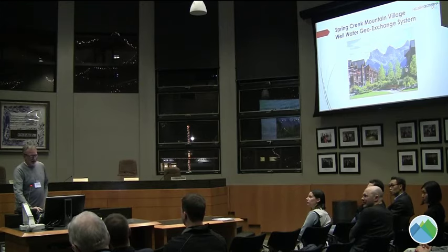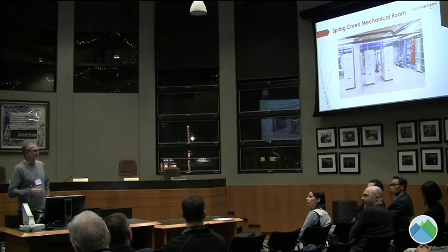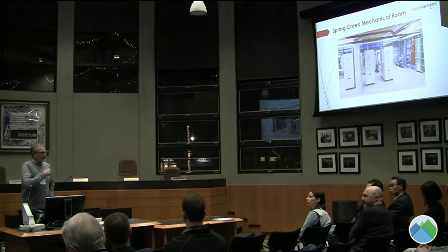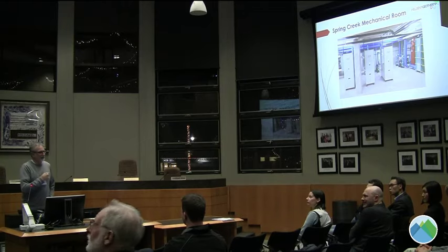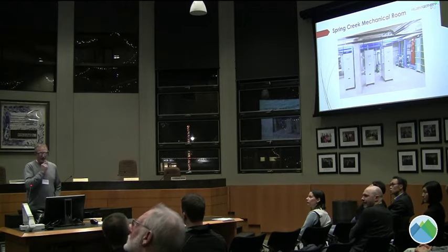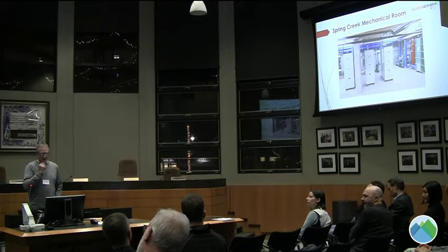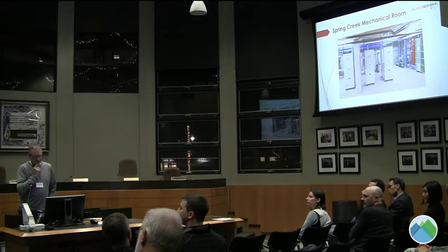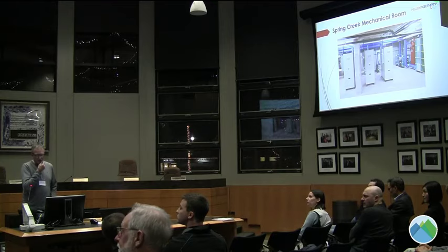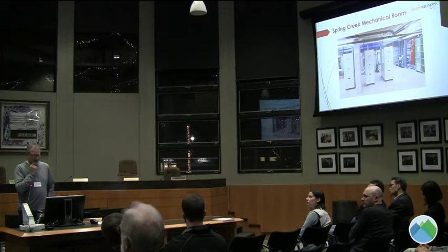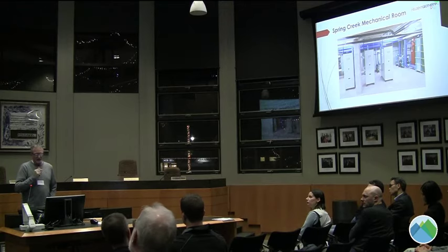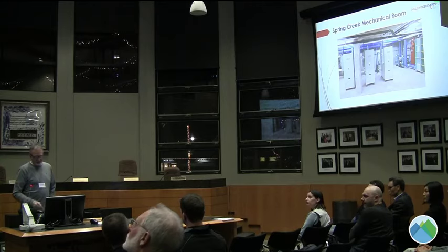Because geo doesn't degrade the water at all. 100% of the water that comes out goes right back in, just a few degrees cooler or a few degrees warmer depending on the season. So it's totally non-degrading, and there's no contamination or anything like that at all. So this slide is just of one of the mechanical rooms of a 50-unit apartment building down there. It's a 90-ton system, so it's 3 30-ton heat pumps, and you can see the heat exchanger and the pipework in the background.